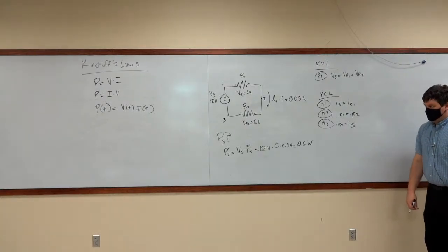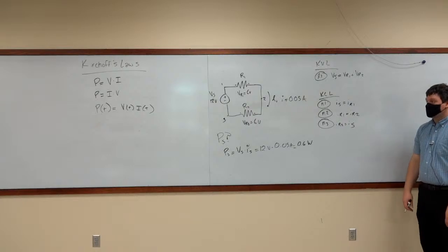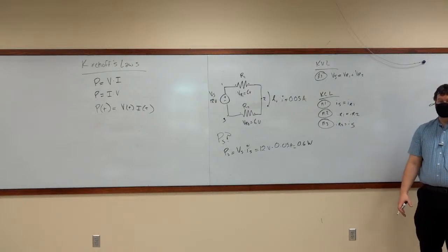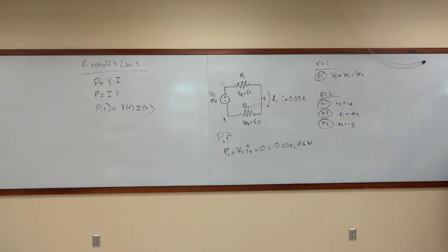Now, question. If I add the power that's being consumed by R1 and R2, am I going to get 0.6 watts? Why? Take away 0.6 watts by the end. Conservation. It all has to do with the conservation of energy.